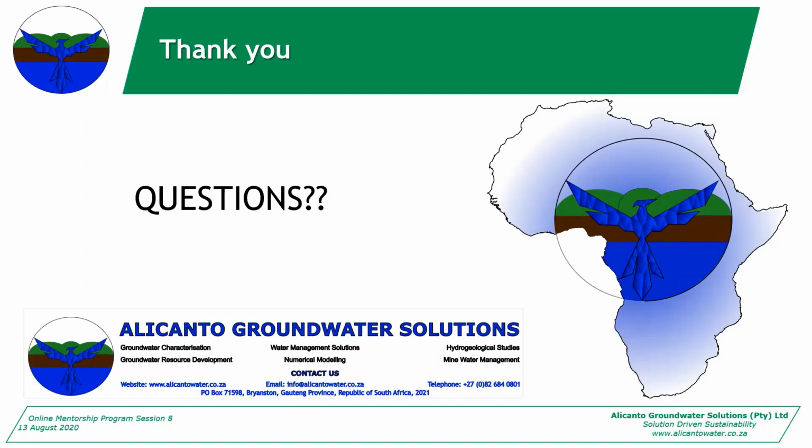Exactly that, Victor. If you've changed it during calibration within the realistic range that you've determined from your desktop review and initial data collection, then it's fine. Then you can just carry on with your modeling. But if you've changed it and it's outside of the range that you determined, then you need to do additional work to refine your data set and get a more representative and realistic recharge value. Or you need to look at your calibration again and stop fiddling with recharge if you can't do that.